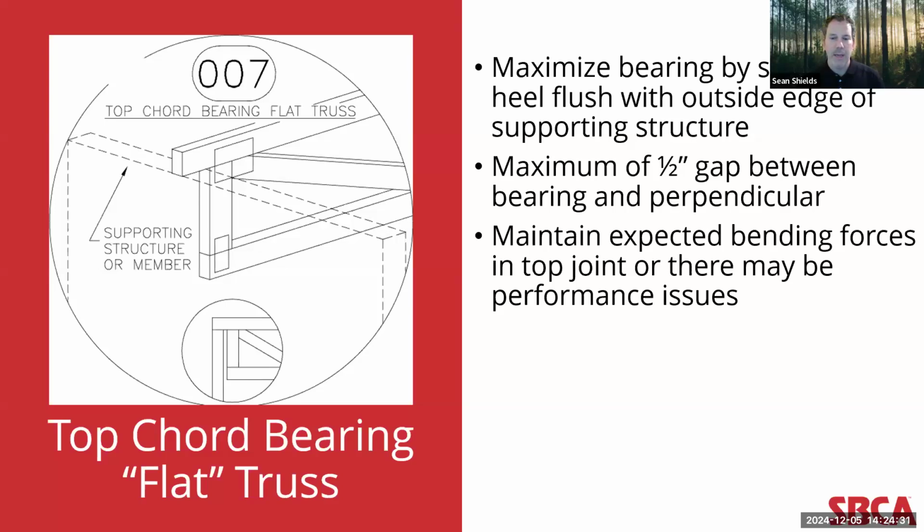For example, a 1 inch gap would double the bending forces going through the joint at the top chord. Depending on conditions, that small change may cause serviceability issues later in the building's life cycle. I'll give you an example.